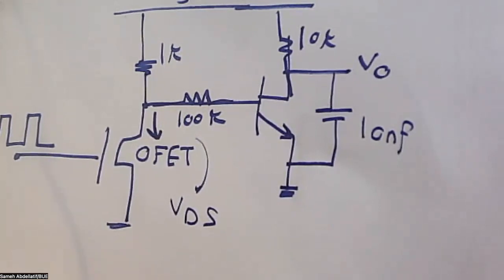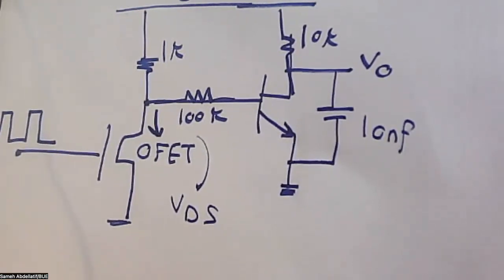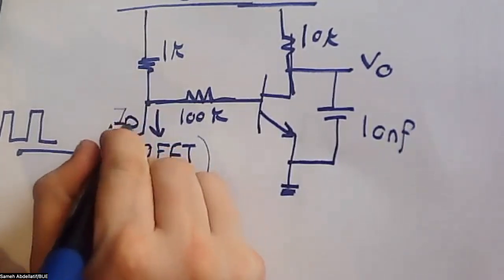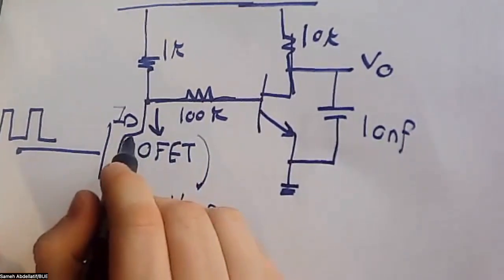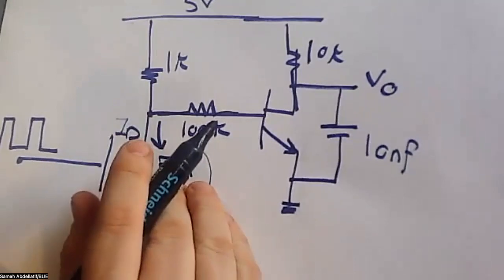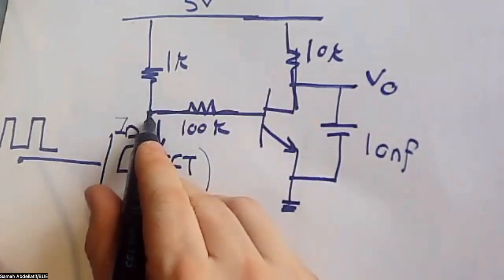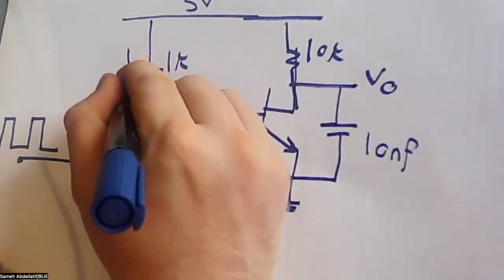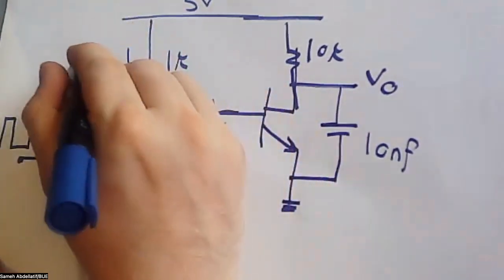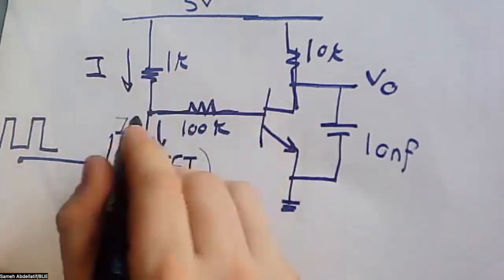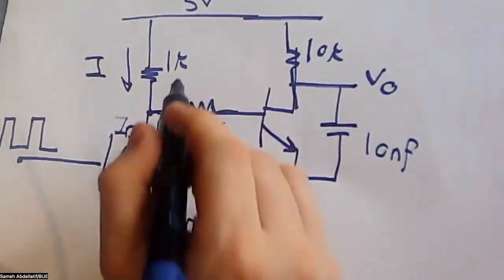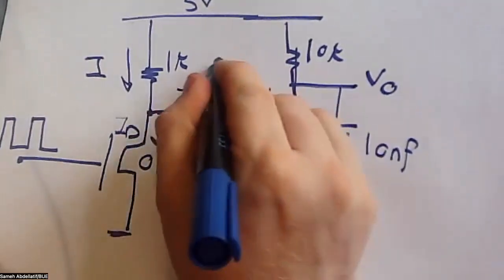As you can see, using a nodal analysis here, you can say that the current flowing here, which is ID, is simply a part of a total current flowing from the source to this node. So the current here, let me call it I. This I is going to be branched into this ID, and another part which will be called IB.